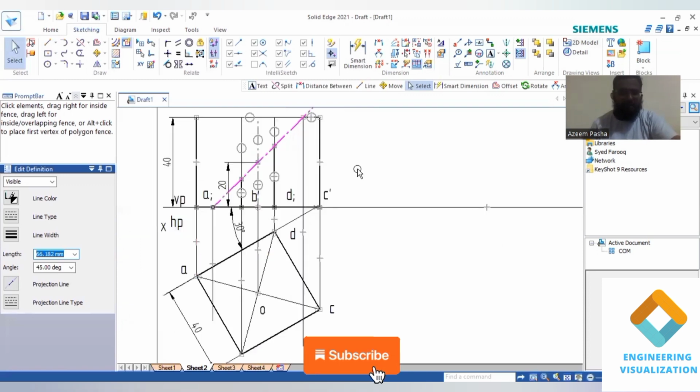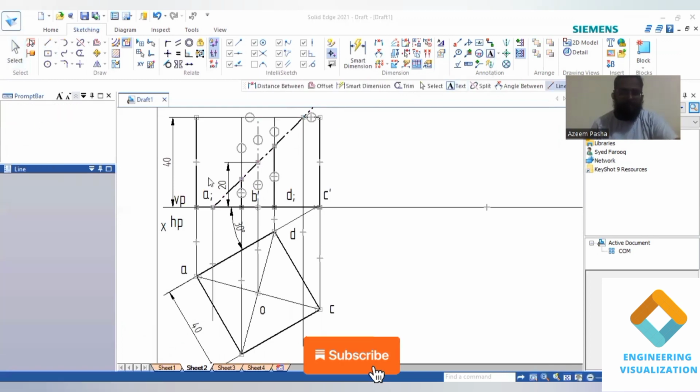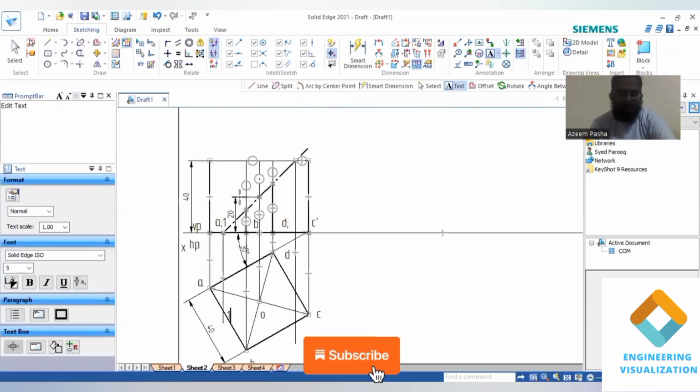Now you can give the numerical numbers where we have cut the section plane. This is where the cutting actually started, so I'll mention this as 1, and it is occurring in between the vertical edges of A and B. So this is 1, and I'll mention this is 2. The point number 2 is exactly occurring at the edge B, and then point number 3, we are getting exactly in between B and C.